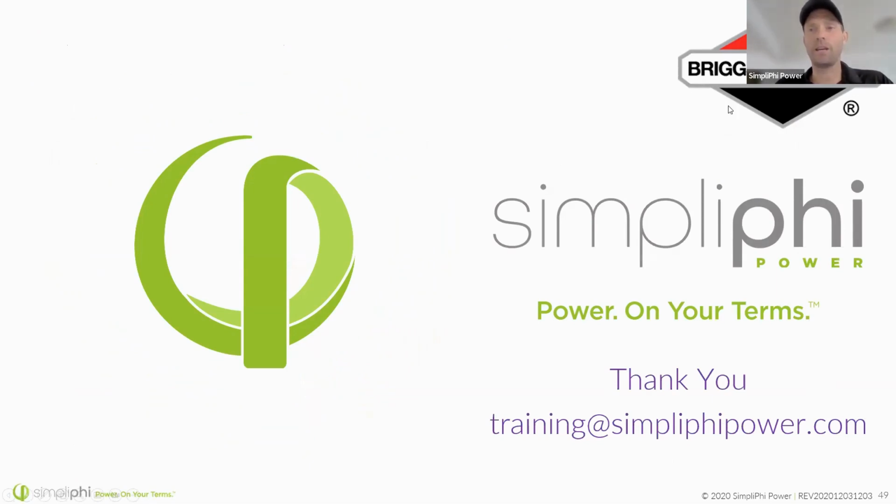I'm going to jump into the Q&As. So Kuno, you asked about why 24-volt batteries might appear at 26.1 volts out of the box. They come discharged, and the reason that they're shipped discharged is there are UN regulations around shipping batteries. They're not supposed to be at high states of charge. It makes the batteries safer to ship them at a low state of charge. Unfortunately, we can't top them up for safety reasons before they leave the factory.